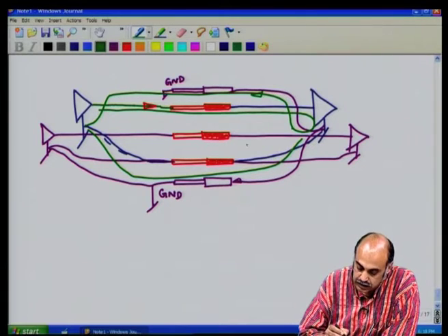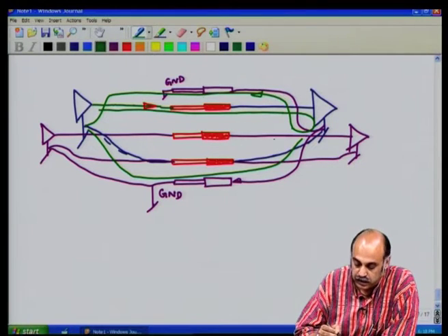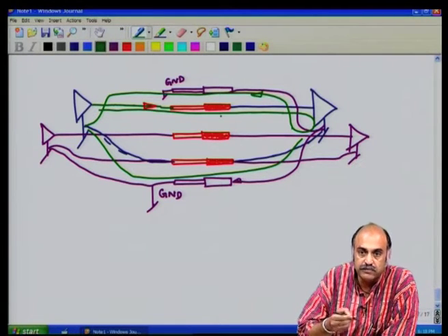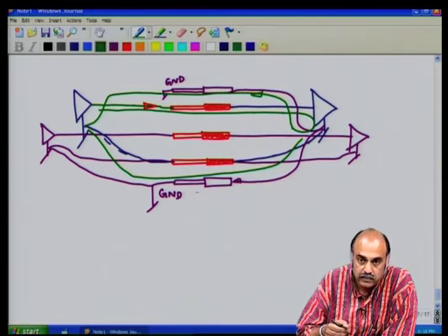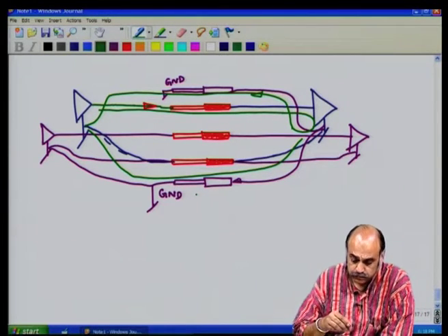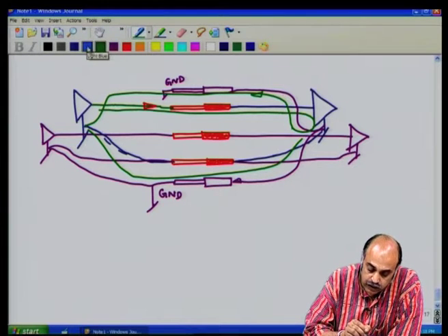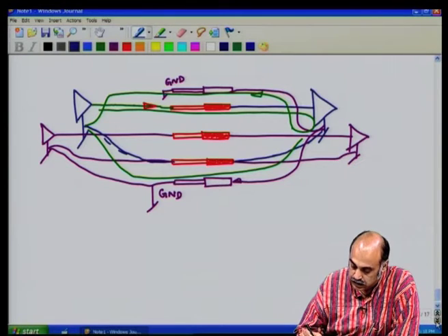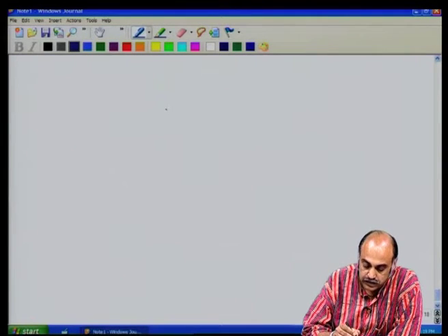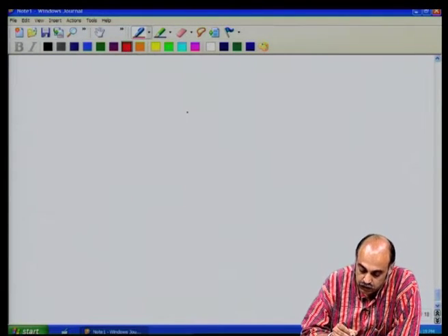Now, what happens is that through each of these grounds only part of the current flows through, and the strength of the magnetic signal is lesser, and as on one side it is clockwise and on the other side anti-clockwise, you have some cancelling effect. So, this is one way of putting grounds on the outer side of the connectors, which are supposed to have crosstalk.